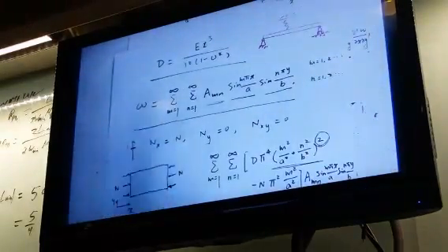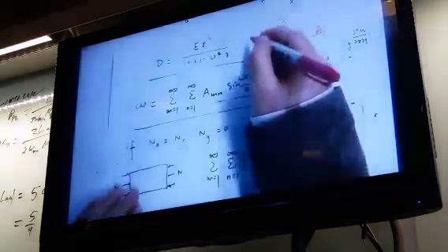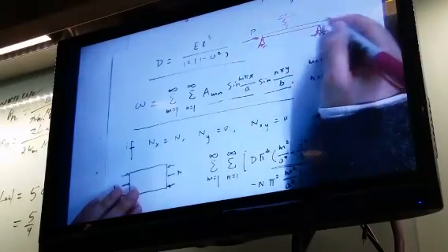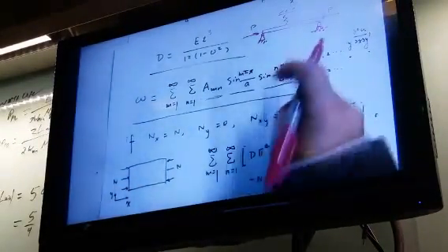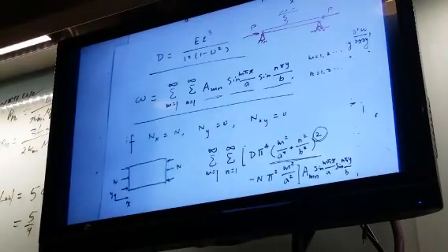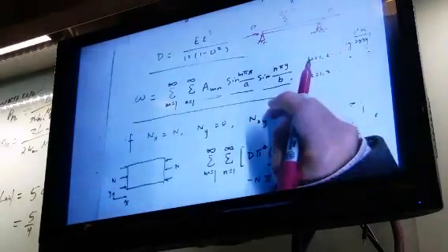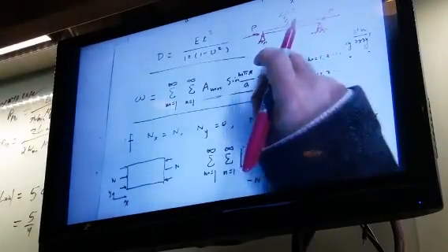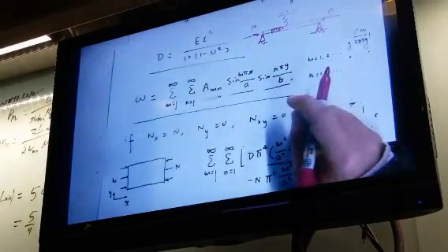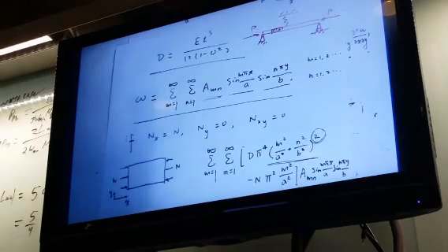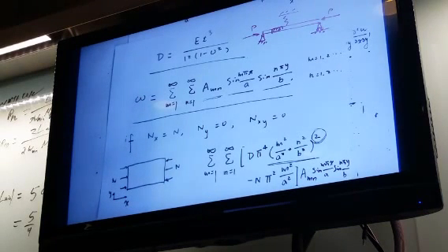And I'm asking you to derive what the critical loading is for this column to be buckled. So the Gaussian equation cannot be used directly for this setup because we need to start with a free body diagram. Take one segment of the beam and draw what is the force acting on each cross section, what is the moment acting on each cross section, do the moment balance.